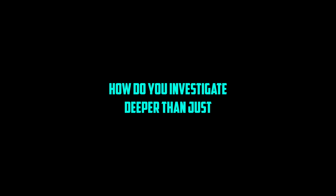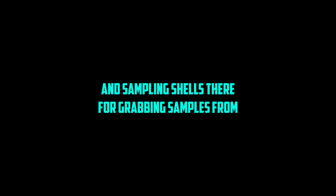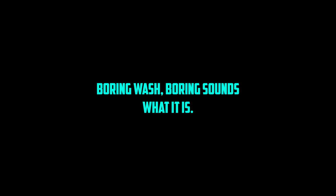Subsoil sounds key. How do you investigate deeper than just a shallow pit? Good question. Trial pits are fine for the top layer, visual checks. For deeper stuff, you might use a mechanical auger like a big drill. Yeah. Different types, sometimes needs a liner or casing to stop the hole collapsing. Okay. And sampling shells. They're for grabbing samples from shallow to medium depths, but not in solid rock. Then there's wash boring. Wash boring sounds wet.